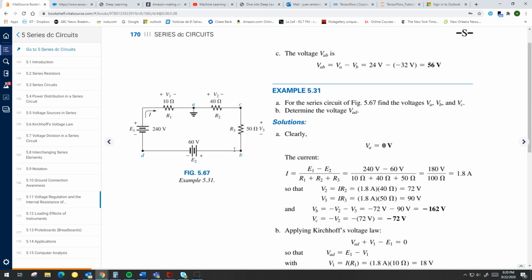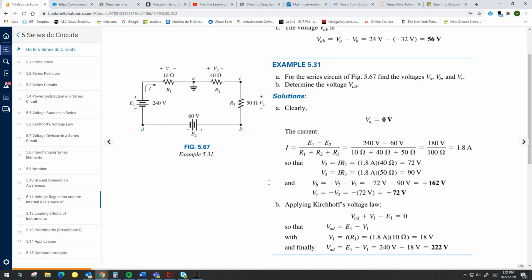And the voltage at B, where is B? Here. B with respect to ground. Imagine putting a meter, one lead at B and the other one at A. Look at what you'll be measuring: the voltage from here to here. Or you can go the other way, in this direction, with one lead here and the other one here. So you're really measuring either this portion or that portion of the circuit. It won't make a difference for the value of B and C. So let's find those values.